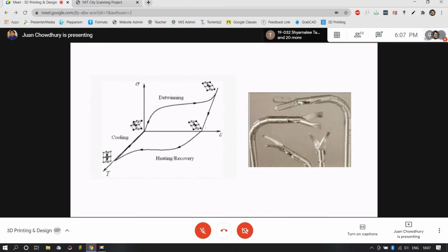Okay, you reorient the part from there. So as you change from a martensitic stage, you start applying temperature, it slowly goes to what? An austenitic stage. Okay, so it will bend, right? And eventually this whole curve can be plotted as you change the stress also, which means if you have put any mechanical stress in the system.